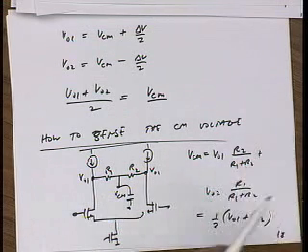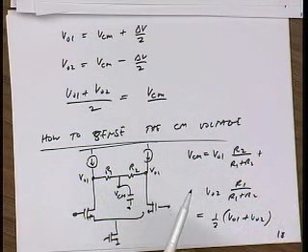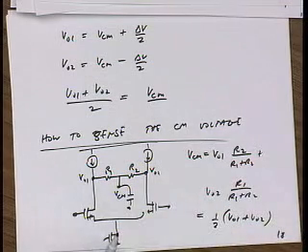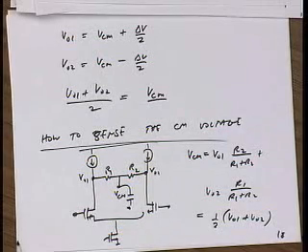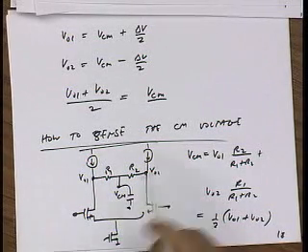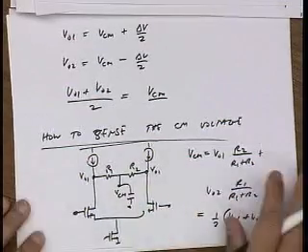And then all of a sudden the amplifier needs a second to get the right common mode voltage. And in 1 second, the packet is gone, right? The packet came in 1 millisecond, and the whole time the amplifier was railed, it didn't detect the packet, right? So clearly we need a fast enough common mode loop. You can't arbitrarily use large resistors.